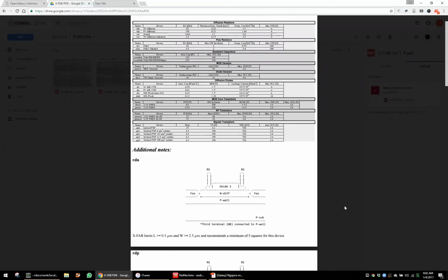I'm going now to only finish the trimming. The pins for the trimming, I normally use separate pins for each signal: 3 in 1, 3 in 0, 3 in 2, 3 in 3. The schematic symbol must be in the digital form, with brackets, 0 to 3 and things like that.